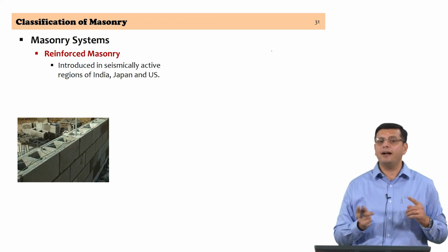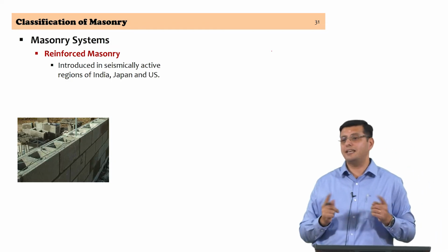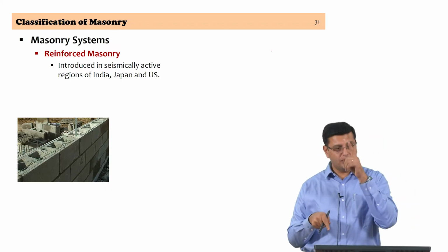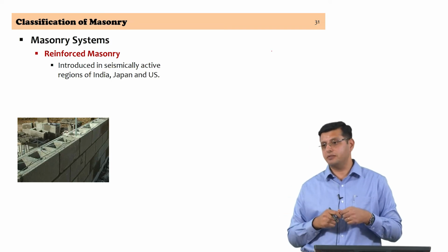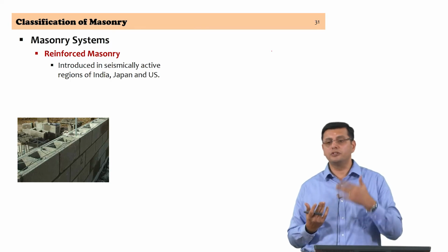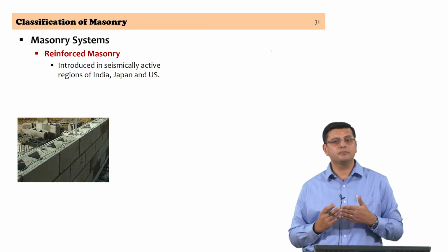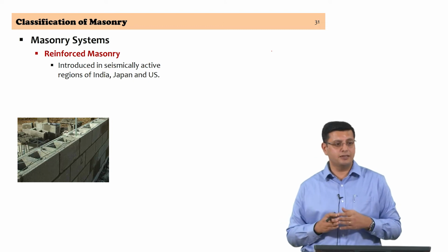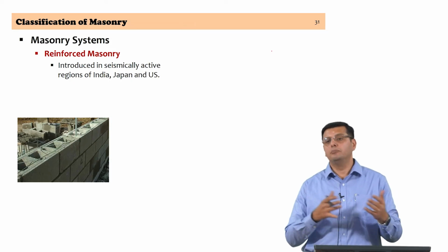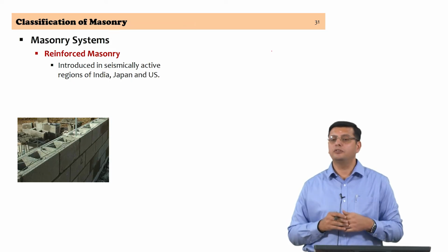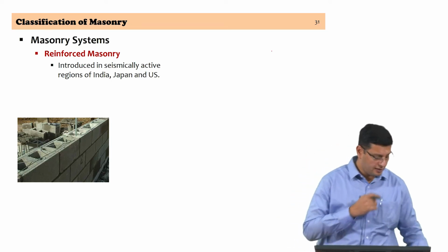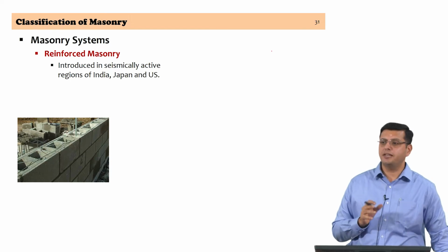So, going back to the discussion on stagger to avoid vertical joints and the need to have vertical continuity for you to put steel reinforcement, this is something that needs to be examined carefully, because you still should not have vertical joints. Stack bonding with vertical joints is not desirable, but you must have continuous vertical cavities, and hence bonds that allow for the formation of vertical channels into which you can have reinforcement is definitely a challenge which has to be tackled.